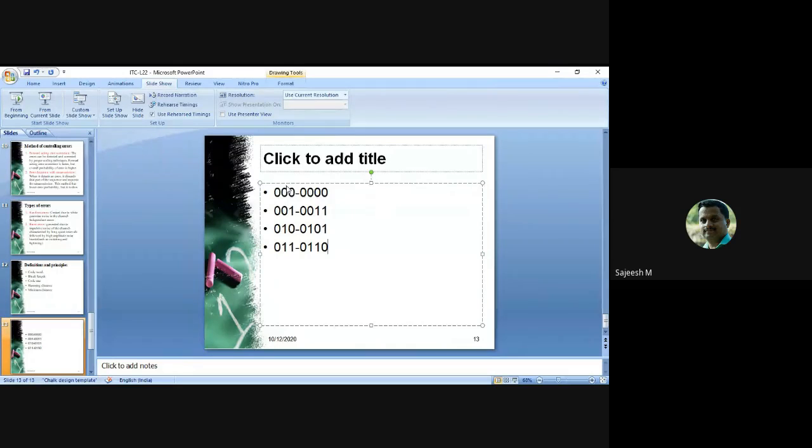Okay, the last bit, here we are adding that extra bit as a parity bit. It is at the rightmost of the code word. Therefore, a 3-bit message is converted. That is, if it is 111, then the code word will be 1111. That is an extra bit in order to make an even parity check code.